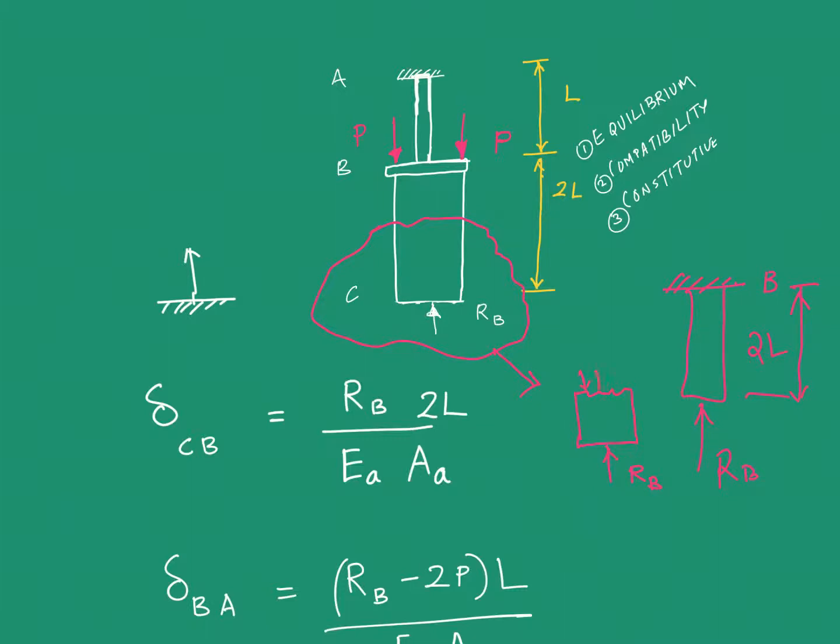Then I will have some resultant distribution, the stress distribution or whatever, on this face, whose resultant will again be RB. For this particular portion to be in equilibrium, this is the net force acting in that section. That's why we saw an RB in this expression.